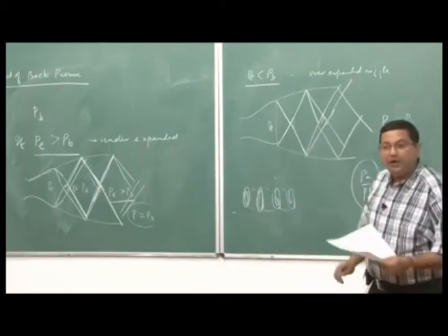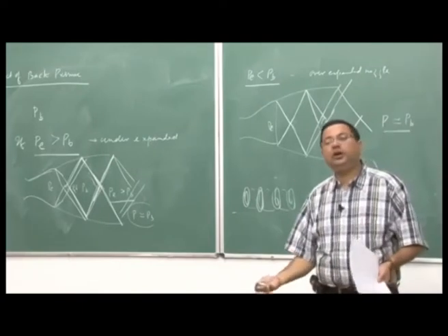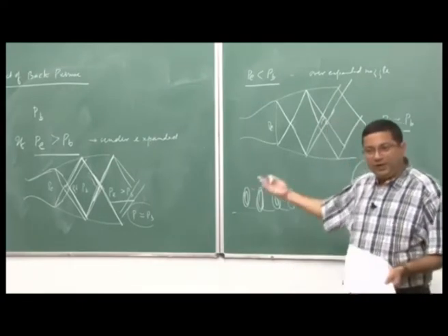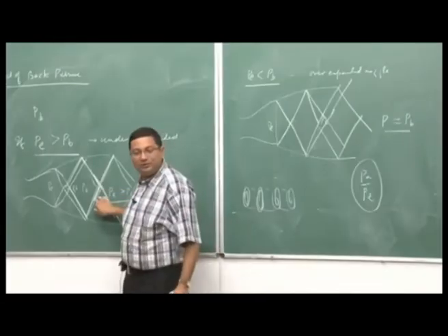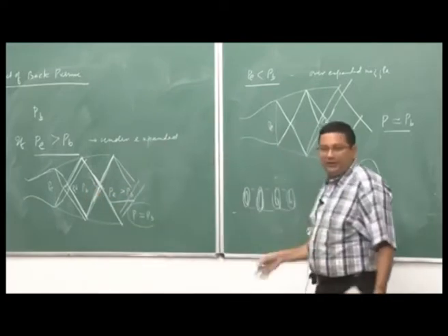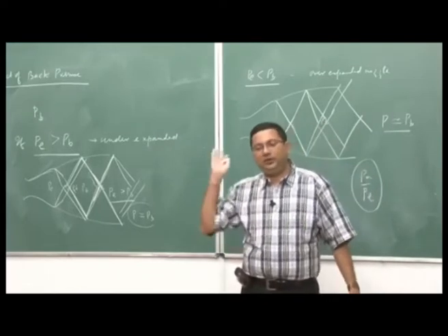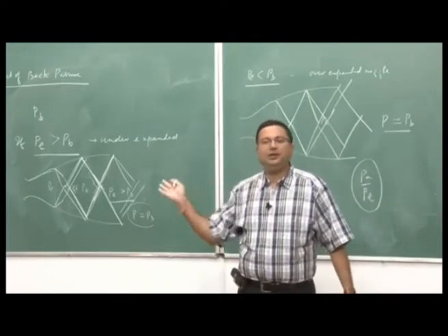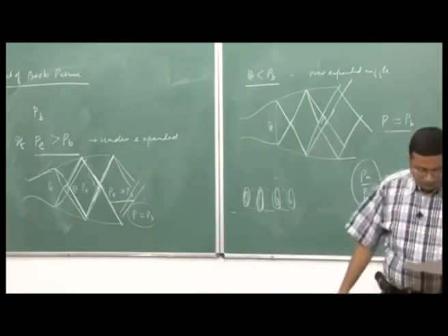And another point is that across the shock waves there is going to be a lot of shock-induced losses. So, when we have shock waves, the losses increase, and we can see the shock wave is present here also, right. Here also we have shock waves, here also we have shock waves. So, finally, the thrust is going to decrease. We have discussed that in detail, that is why when we have ideal expansion, the thrust is maximum. On both sides there are going to be losses.